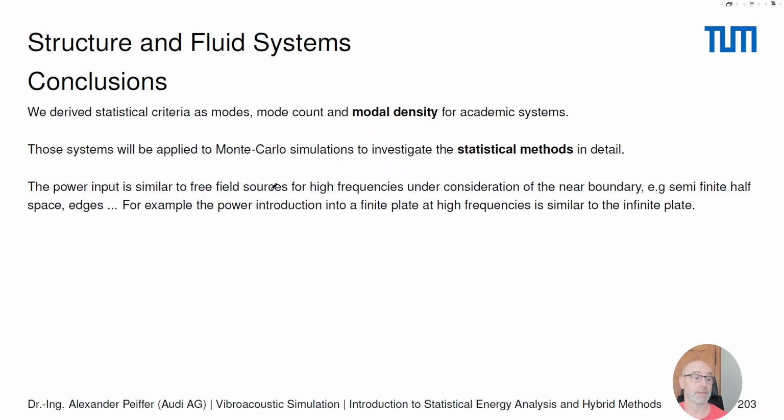The power input is similar to free field sources for high frequencies. Under consideration of a near field boundary, that means if we have a large system and put, let's say, a loudspeaker at the wall, or if we use a force on a plate, then for high frequencies the radiation and introduction of power is the same as for an infinite plate.